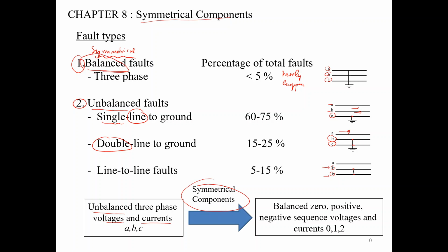Most of the time when we talk about three-phase, we assume that the system is running in balanced condition. In balanced condition, that's why we could analyze per phase. When we want to analyze a circuit, we normally use the per phase analysis.